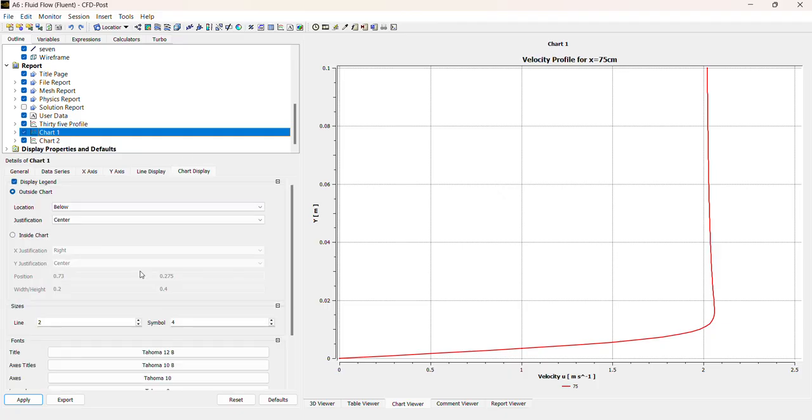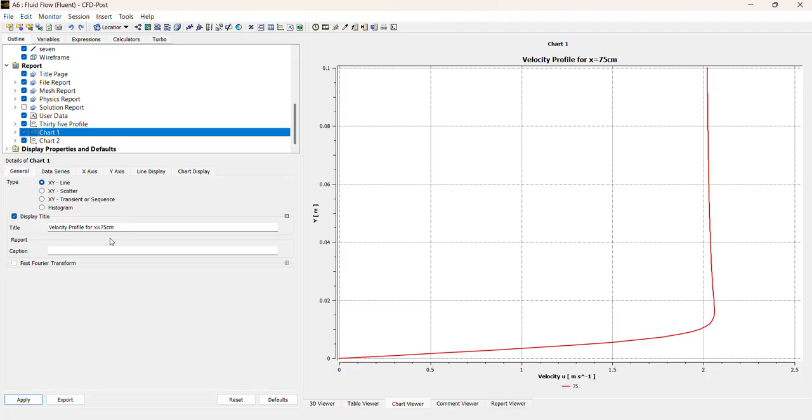Line display, this part is relatively simple. As you can see, I capped it at 0.1 because if I went all the way up to 0.5 and everything like that, this becomes extremely small and kind of hard to see. Here you can see the velocity profile in a kind of linear fashion. You can tell it's getting larger and larger, so it will start like this and go all the way up diagonally. Here you can see the boundary layer where it reaches 2 meters per second. Once it passes that point, it has turned into a fully developed flow.